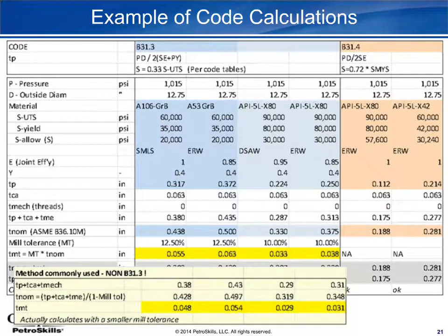In today's manufacturing technologies, with the advances in metallurgy and making steel, we have been able to come up with a dual spec product, 304/304L, meaning it meets the strength requirements of 304 flanges, and it meets the corrosion resistance after welding of 304L flanges. And we just have to be cognizant that if we are utilizing the strength of that dual spec material, we need to spec it as a dual spec material and realize that it is not an either-or situation. Great question. Okay, thank you, Stu.